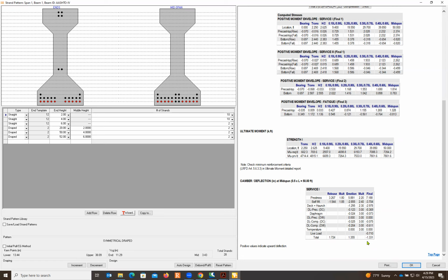And for design, we do not want a sag curve for typical bridge girders. The ideal scenario is that after all the load applies, we still have a positive, or upward, camber for the entire bridge in order to make people feel safe driving under the bridge. So we try to avoid a sag curve for the girder line.